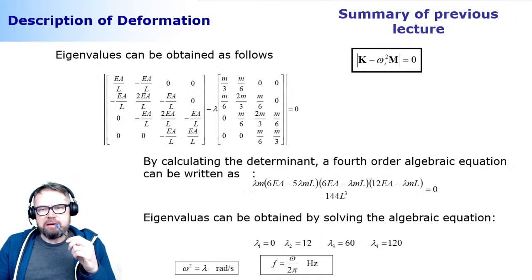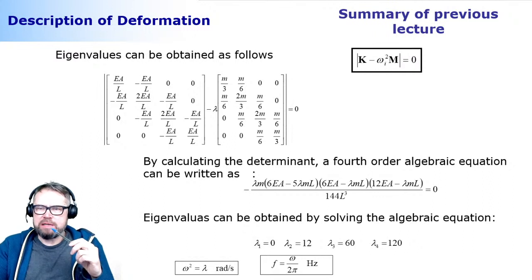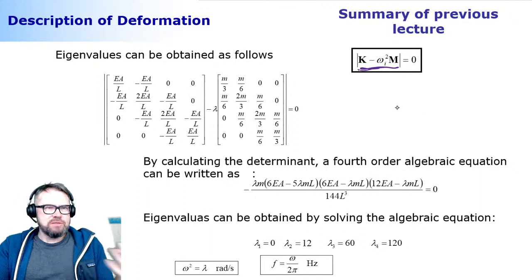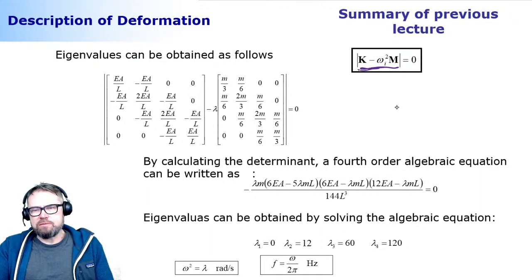Now I'm showing the classical way to conduct an eigenvalue analysis. First I'm computing my eigenvalues by solving this part of the equation, taking the determinant of this equation. For sure you cannot do that when the dimension becomes very high, but here, for the sake of demonstration, I'm showing how it goes. I get a fourth order polynomial.